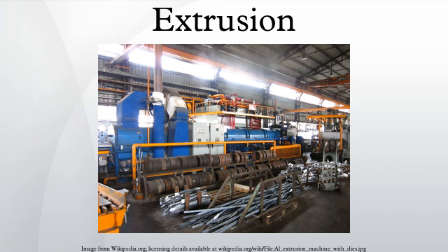The disadvantages are, the billets must be prepared by tapering one end to match the die entry angle. This is needed to form a seal at the beginning of the cycle. Usually the entire billet needs to be machined to remove any surface defects. Containing the fluid under high pressures can be difficult.